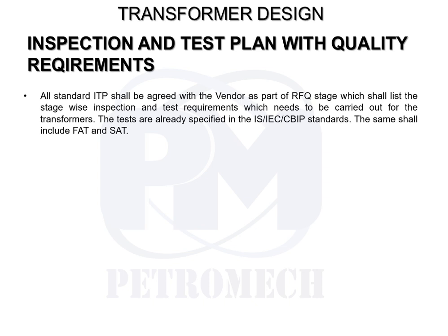we have to take a proper compliance from the vendor on this inspection and test plan. This varies from organization to organization based on their specific requirement. However, the main important points which shall be part of the ITP in terms of testing are already laid down in the IS, IEC and CBIP manual. So anyone who wants to look up what tests have to be mandatorily performed, that is, routine tests on any transformer assembly, these are clearly mentioned in IS 1180 and IS 2026 standards based on the transformer rating.